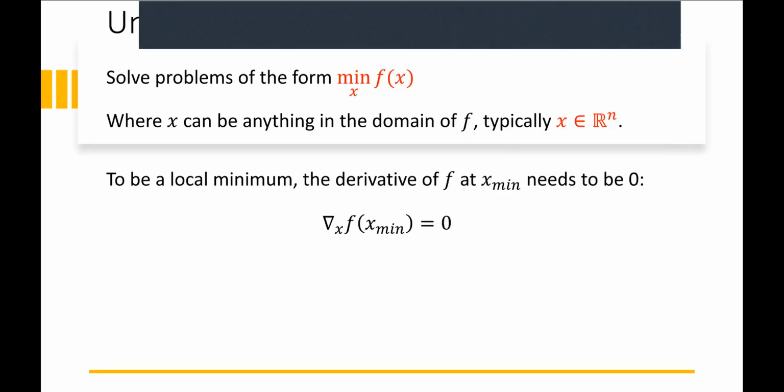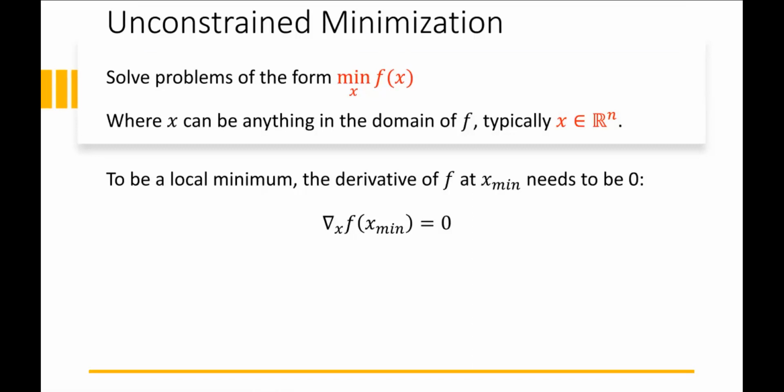So if we have this error function, for any single proposed joint configuration, I can just run forward kinematics and figure out where the hand is. And then I can figure out the distance between that position and the position I want the hand at. But I still have to generate these potential joint configurations.